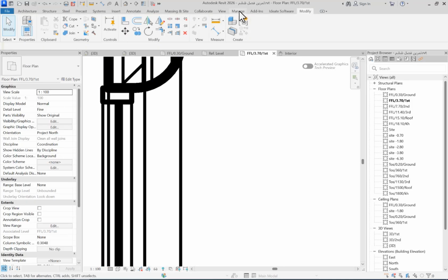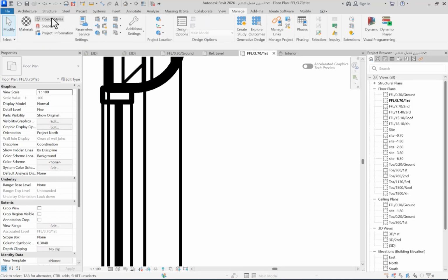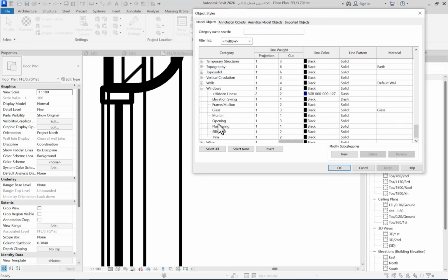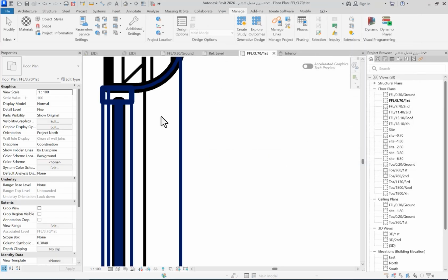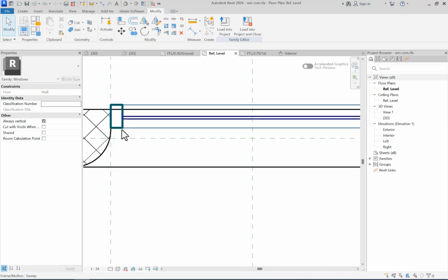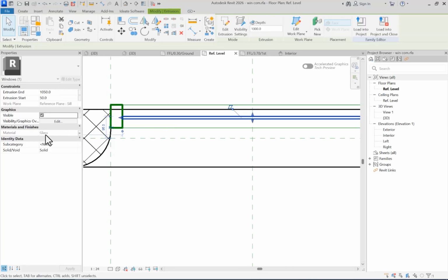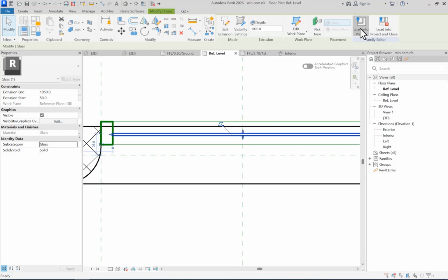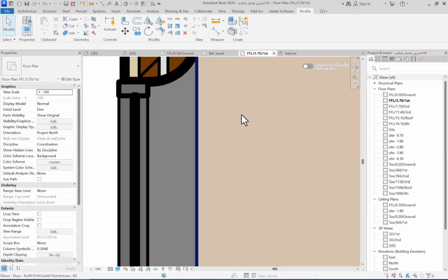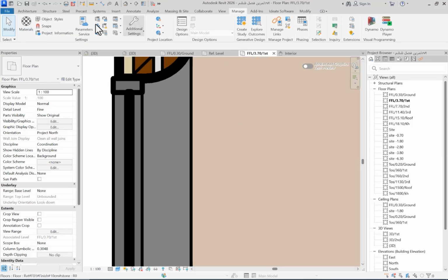As I mentioned earlier, guys, by not specifying the subcategories, the whole thing would have worked according to our Windows parameter, to our main item or object. And well, not only is this unprofessional, but also it's incorrect. So let's just specify the subcategories: frame mullion for this one, and then the glass. And now that I did this, I will have complete control on both the frame as well as the glass. So let's check this out now.